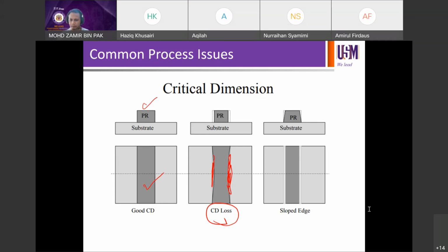Inspect DOF. Before DOF, let's dive into that. This is very straightforward. It has nothing to do with DOF yet. If we get into DOF it's more complicated, then you have to verify the whole thing. This is just whether CD is on target or not, in relation to the printing lines or holes. Sakina? Reduce dose. Okay. Reduce dose to make CD large.